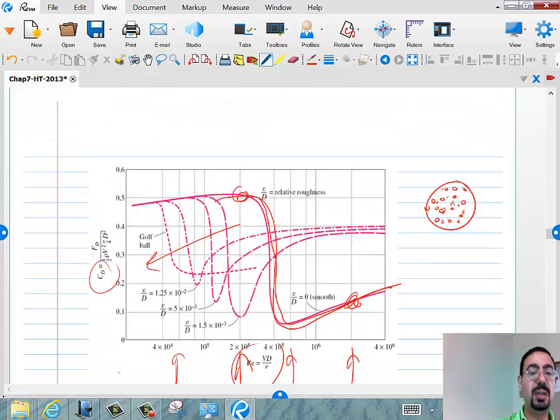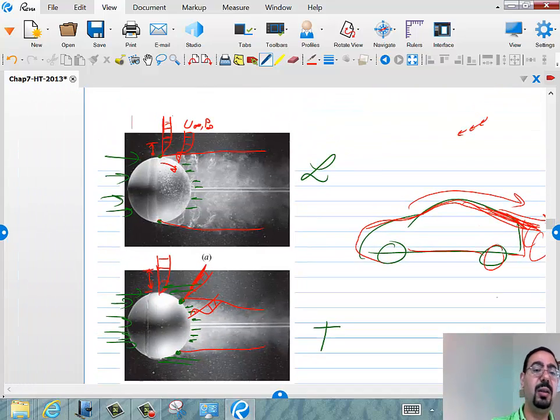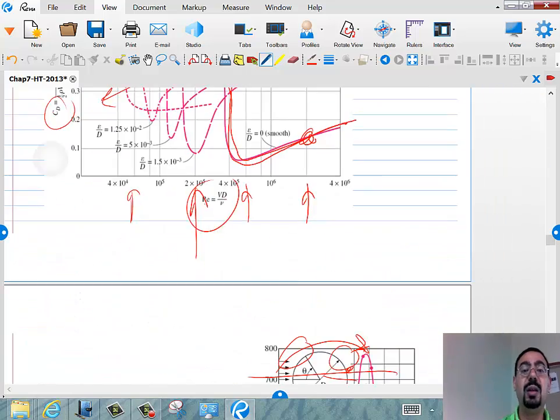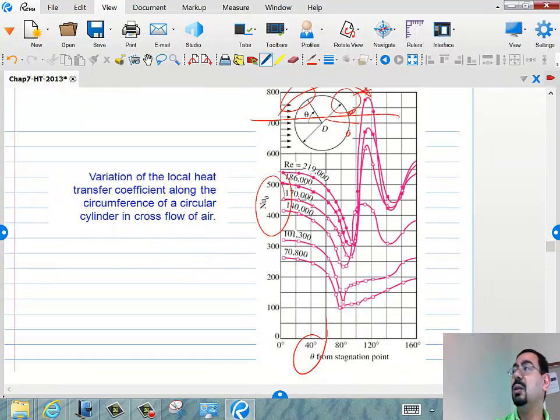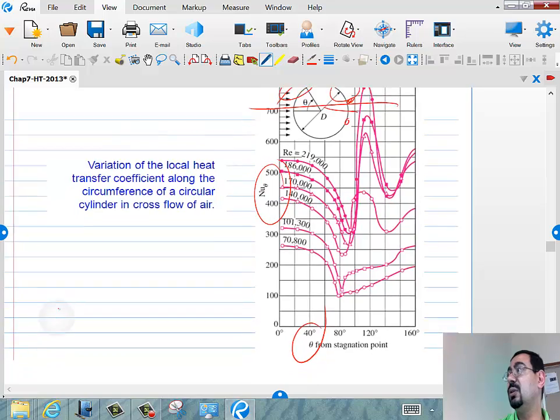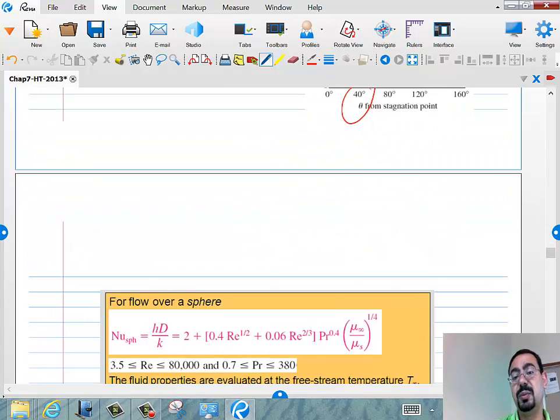So it's because the velocity profile is different, right? The velocity profile here probably will be more full than this one, which is reversed. It's a completely different velocity profile, and if we plot the temperature profile, it will be completely different from one place to the other. And this is evolving as we are moving across from 0 until 90 until 130. The velocity is changing, the temperature profile is changing, and that's why you should expect the local h to be different, right? Completely different temperatures.